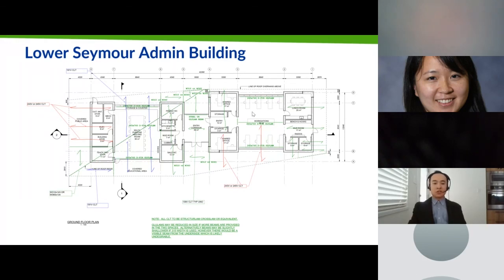So what we had to do is introduce steel beams from inside the structure that projected out to form a front span cantilever and a back span inside the building to pick up those corners so that the CLT can span in one-way direction and be supported by these beams, and then conceal those beams in a manner so that you would not see them, right? And effectively, we have a hybrid structure of timber and steel for this project.